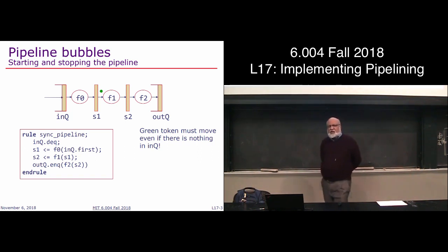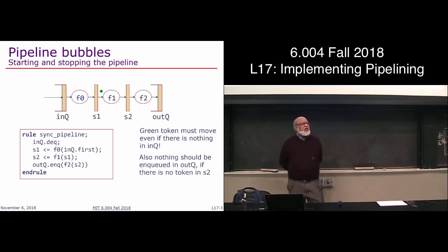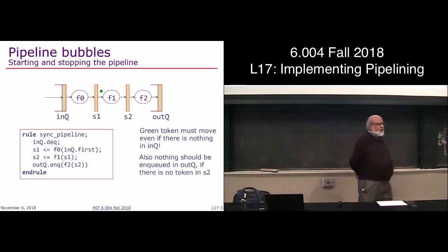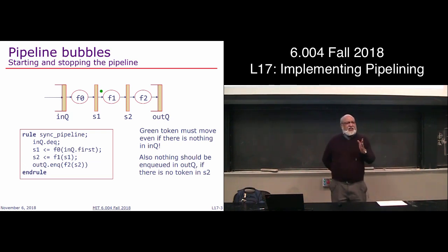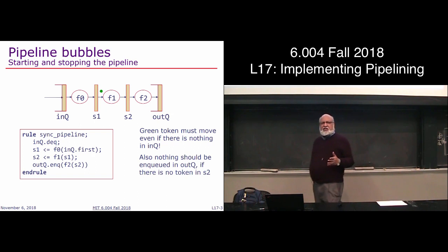And a similar problem exists also at the input side. How do we get it going in this pipeline? But there is also an issue that if I'm not putting something in every time into this synchronous pipeline, then there are gaps, things which are bubbles, things which are invalid inputs, right? I mean, there are invalid values in these registers.